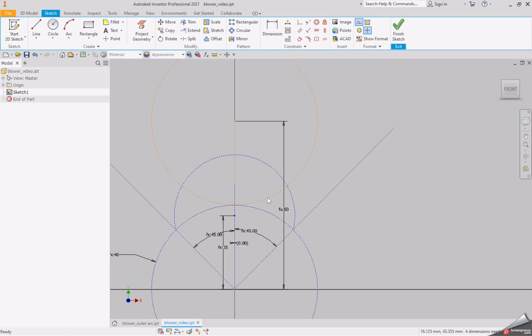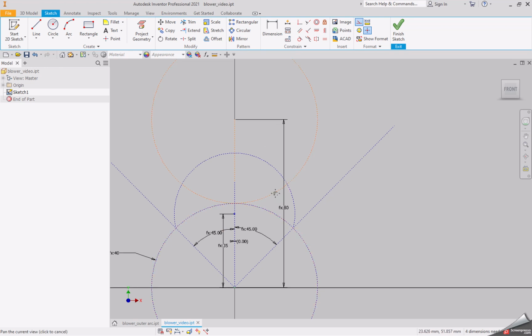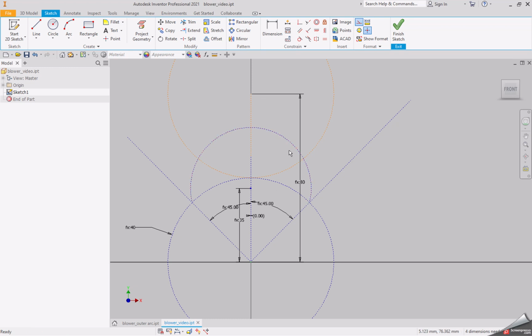And now as this wheel is exactly the same as this one, let's assume that it will be positioned so the lobe is here, and then we will try to find this convex curve that fits on the bottom wheel. So let's get this out for now. Let's define a fixed geometry.